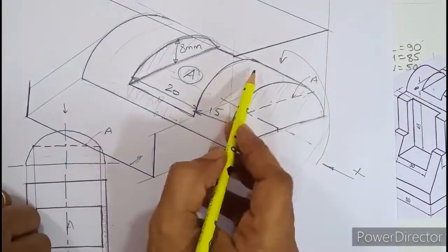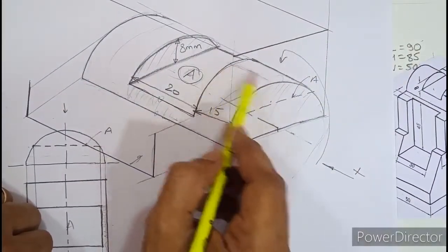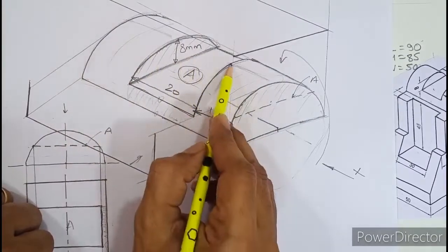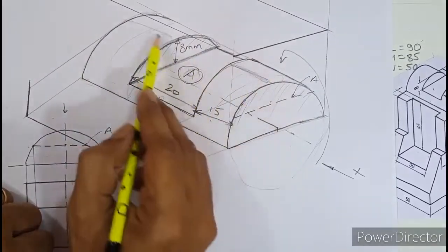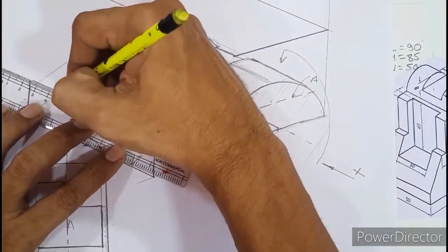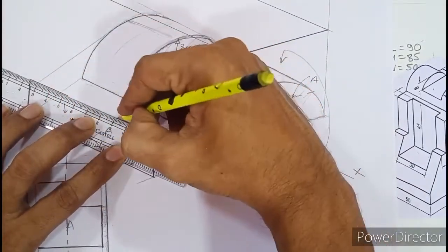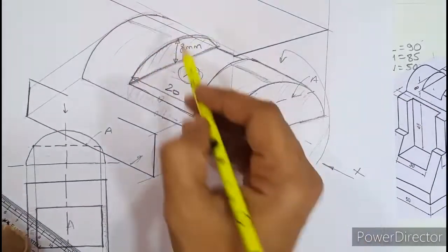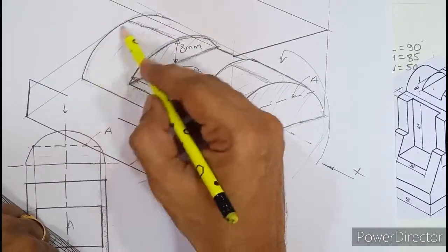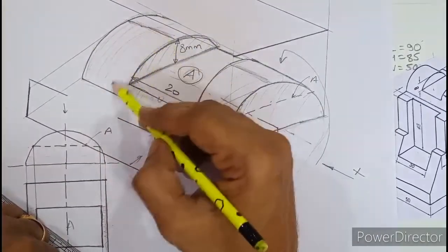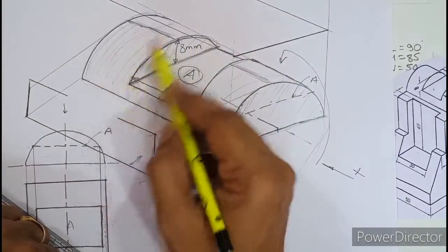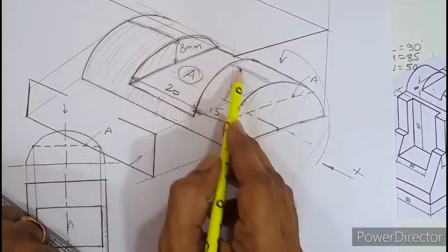Okay, so this boundary of the semicircle will be seen, but it is not throughout because there is a cutout in between. So you can see this boundary 15 mm, it is 15 written here. So up to 15 mm, you can see the boundary dark. So you need to visualize step by step. After you reach this boundary, you can see up to the boundary only, because in the side view, you can see everything above this. You cannot see what is going down. So you can see up to this surface only. So you can see the boundary as a straight line.